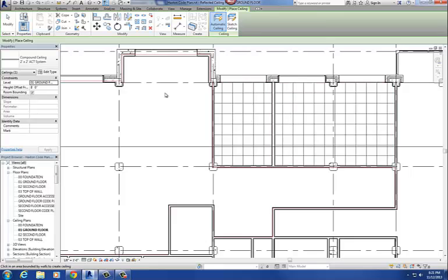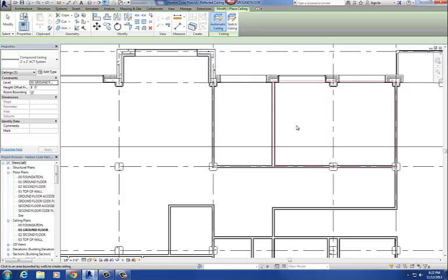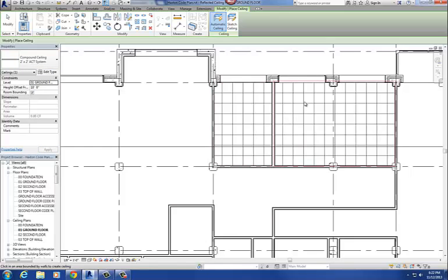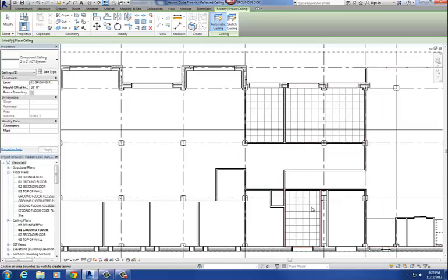Now, before you do that, actually, I kind of jumped ahead a little bit. Before you do that, you want to plan out how high you want the ceiling in those rooms. What we want is 10 feet for our ceilings in our project. So before you start putting in your ceilings, make sure you set your height offset from level to 10 feet. So 2x2 acoustic ceiling, 10 feet, and then you just start putting them in there. Oops, wrong room. That one gets a hard ceiling.